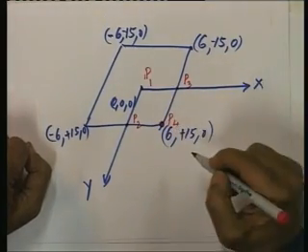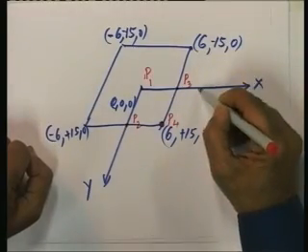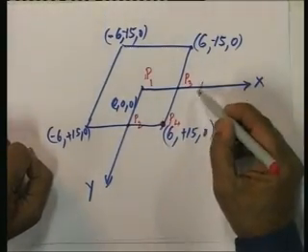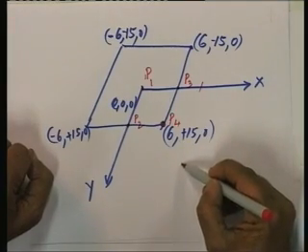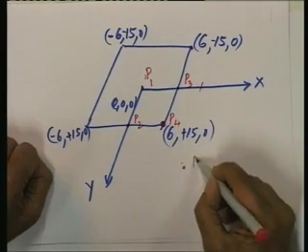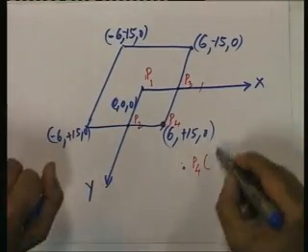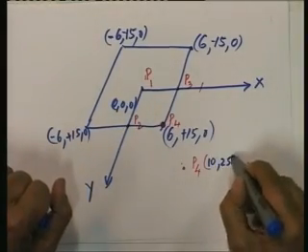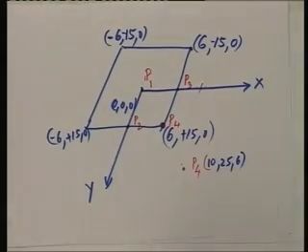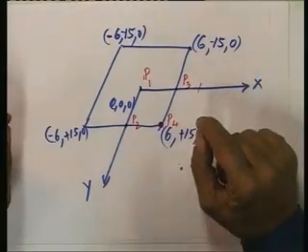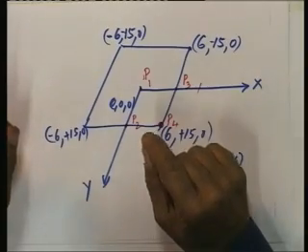Lastly, we have a point at 10 meters along the x axis, 25 meters along the y axis in the positive direction, and 6 meters depth. So there is a point here whose coordinates are 10, 25, 6. Let us see how to determine the stresses beneath this. Remember, we need the point at which we want the stress to be below the corner of a rectangle. That is the starting point.